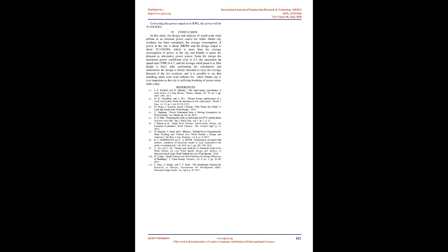Chord versus radius. For this specific design the chord ranges from 0.2 to 0.05, Figure 4, having a decreasing curvilinear relationship with increase in radius. This means the airfoil maintains a smooth curve transition from the base of the blade to the tip. Fig. 4. Radius versus chord.